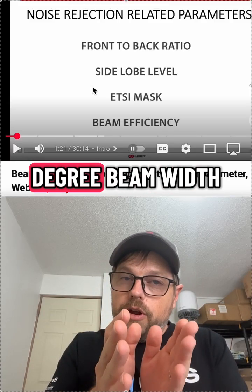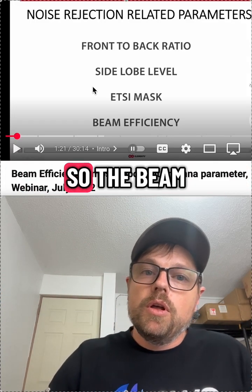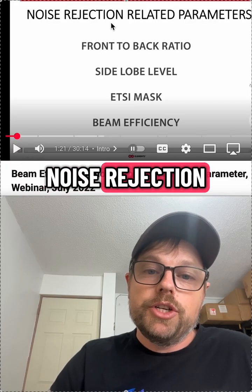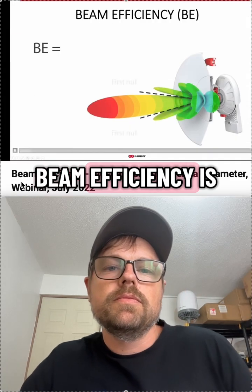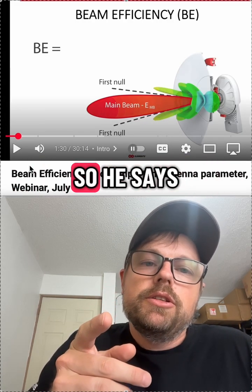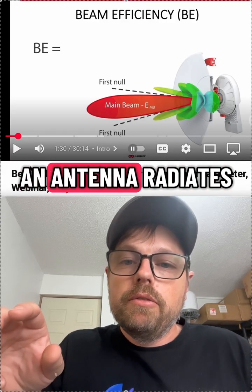Now, if you have a 30 degree beam width, you're picking up a lot less noise and interference from that main lobe. So the beam width is one of the key antenna parameters that you should be looking at when thinking about noise rejection. And RF Elements totally misses that. Beam efficiency is the ratio of the main lobe energy to the total energy an antenna radiates. Keyword there is radiates. So he says beam efficiency is the ratio between the energy in the main lobe, the total energy an antenna radiates.